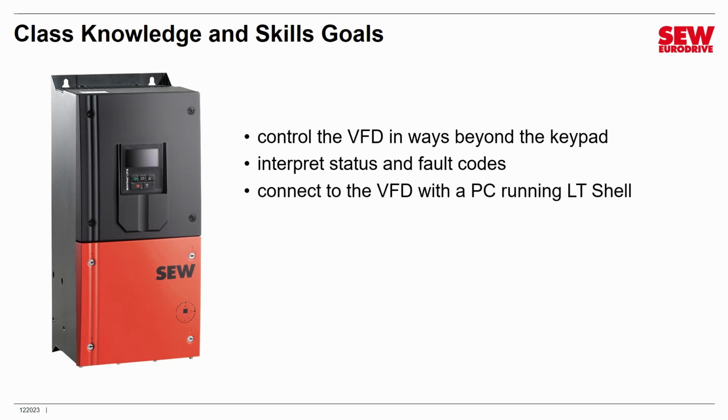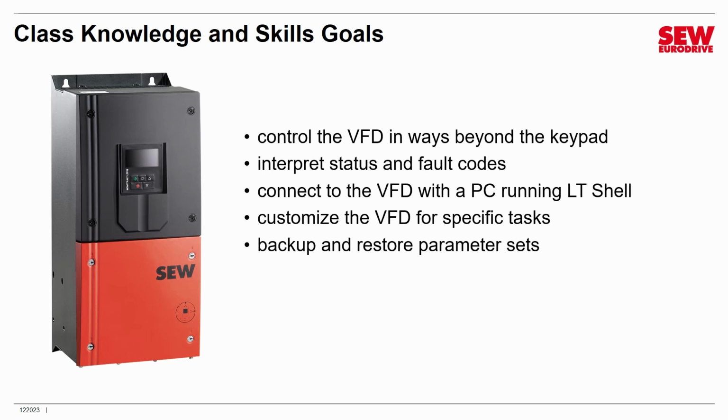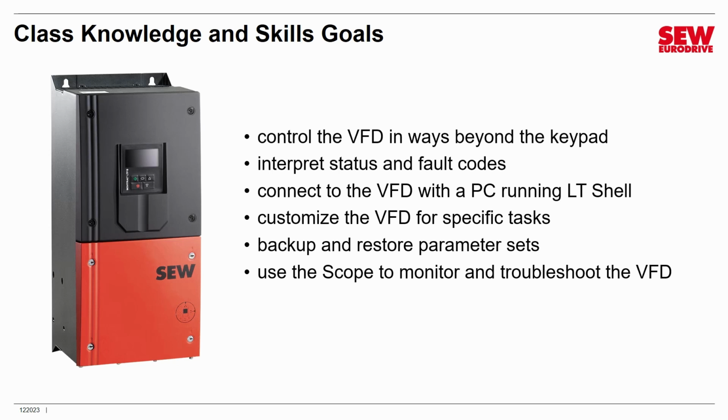You'll learn how to connect to the VFD with a PC running a program called LT Shell, which enables you to engineer the drive much more conveniently than the keypad. You'll learn to customize the VFD for specific tasks. You'll learn to back up and restore parameter sets. You'll learn to use a built-in diagnostic tool called the scope to monitor the VFD and troubleshoot it when things go wrong. And finally, you'll understand fieldbus control, where you can use a PLC or other industrial controller to control one or more MOVITRAC LTP-Bs.